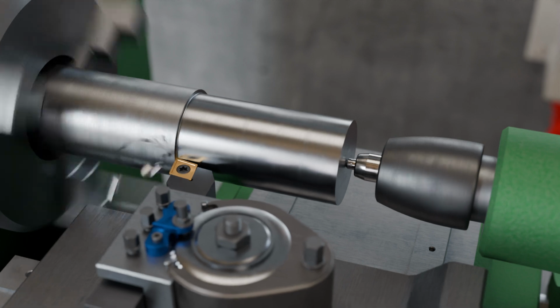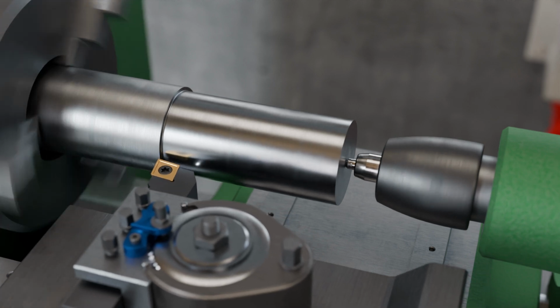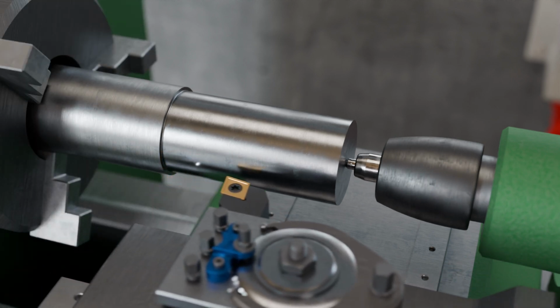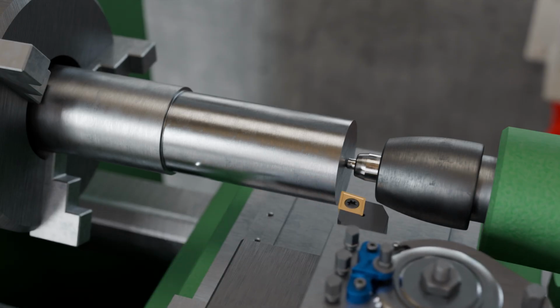However, by selecting an appropriate rake angle on the cutting edge, short breaking chips can also be produced. These segmented chips reduce the risk of long chips getting entangled in the rotating workpiece and causing damage. Additionally, this greatly improves workplace safety, as no long chips are thrown around. Depending on the application, turning can be performed with or without coolant.